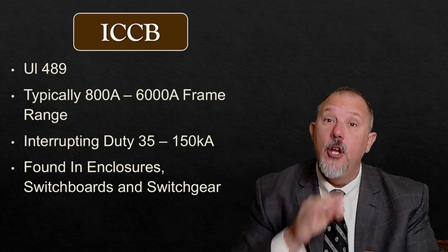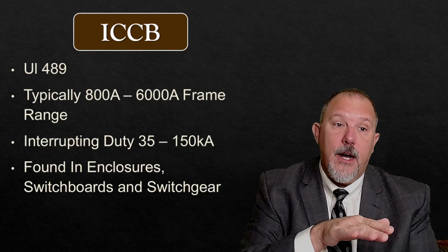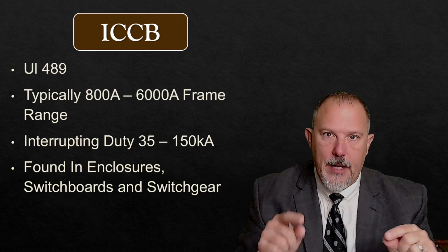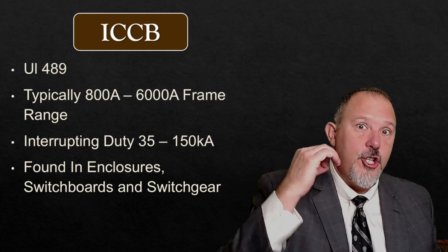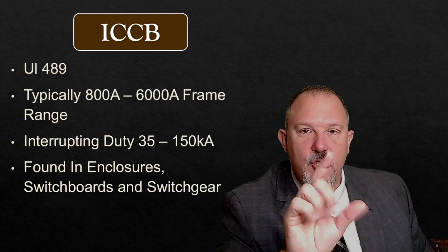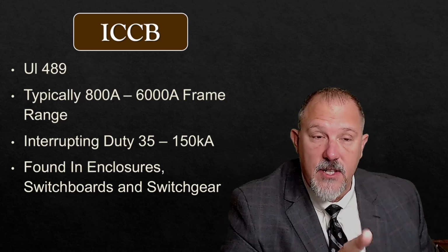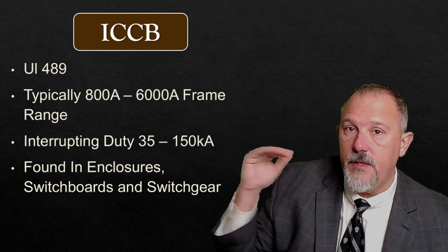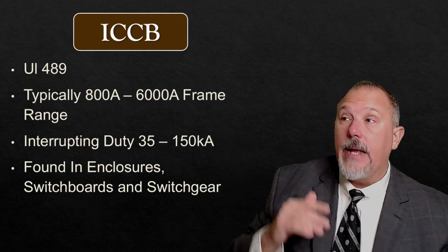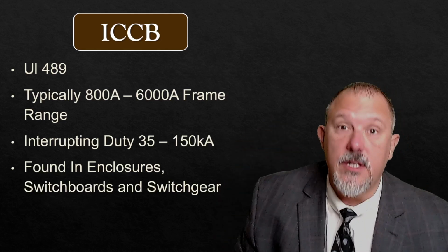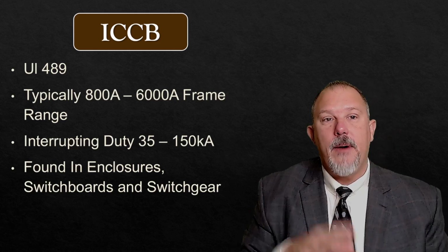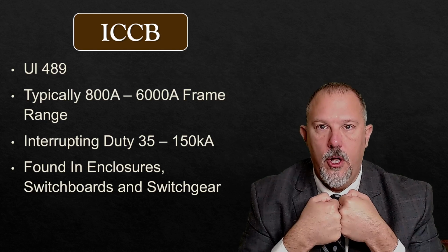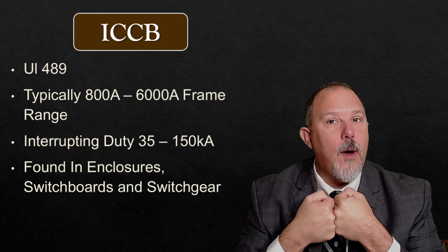And I'm going to show you trip curves for a specific insulated case power circuit breaker and a molded case circuit breaker a little bit later in our discussion that will help you understand the differences between these 3 devices. Suffice it to say, I'm going to see insulated case circuit breakers closer to my service entrance equipment and sometimes in my service entrance equipment. And the reason I buy an insulated case circuit breaker is because I want to keep those contacts closed longer for higher fault currents.